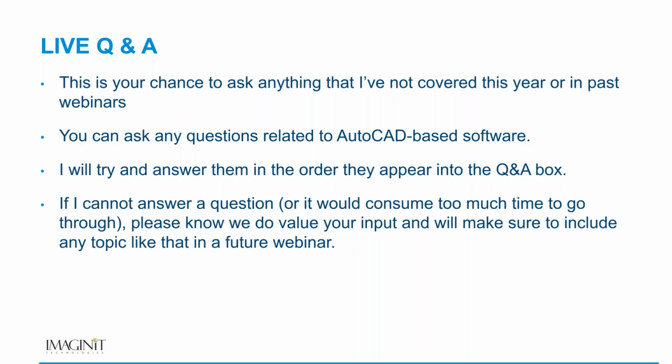Is there no way to stop erasing of the SV$ files? I wish there were 10-minute increments. There is no way to stop the erasing of the SV$. As soon as you hit save, it's gone, or if you close the drawing without saving, it disappears if you have an autosave.